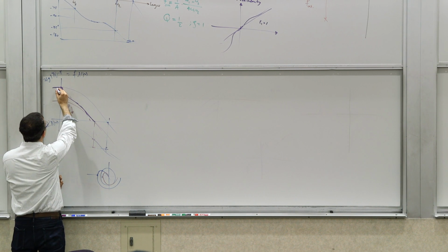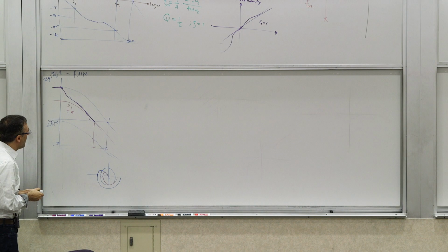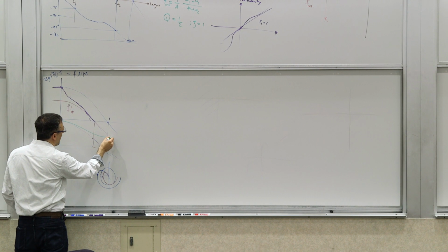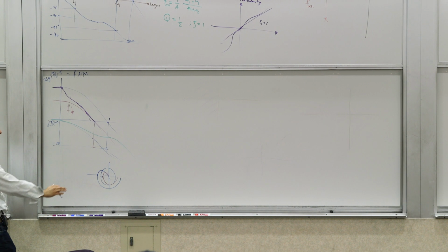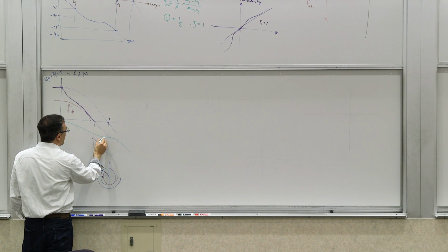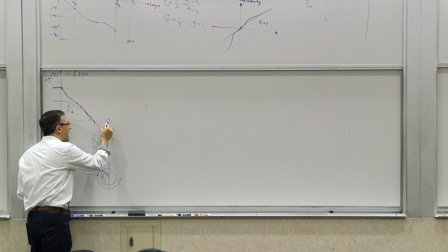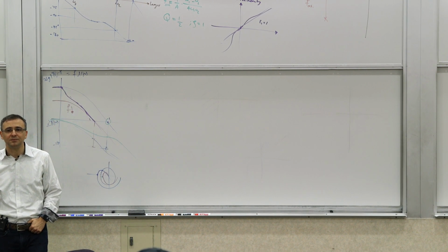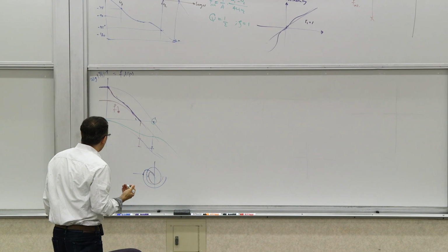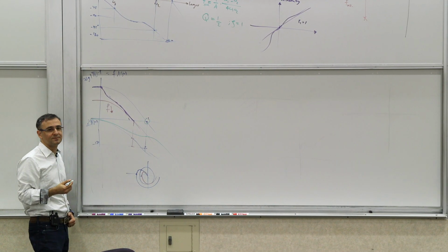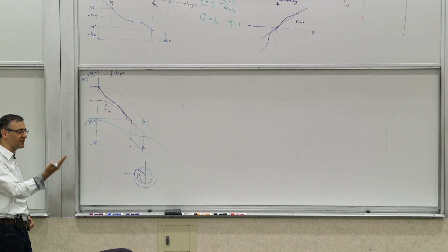What else can I do? Let's say I wanted to stay on this blue curve. Can we do something to the phase part of this thing? Well, if somehow we could push this phase part up before it goes down, so eventually if it goes down, that's fine, but I push it out temporarily here, so by the time I'm getting to the unity gain point, I'm still high, and after that it can do whatever it wants. That's another way of doing that, right? How would you do something like this? What would be the elements that would allow you to kick the phase up?